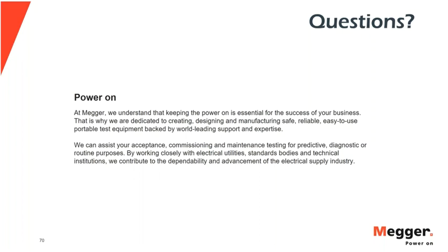Thank you, Diego. Another question for Diego is, what standard lists 0.5% as the limit for power factor of mineral oil filled transformers? That is a very interesting question, because on the standard, you will not see that it's the recommended limit. It's a suggested value to consideration. One of the most important things that you need to think about is not just the limits published by standards. Power factor is more a historical data analysis. You should do some trending analysis on the power factor value. It's not just the 0.5%.